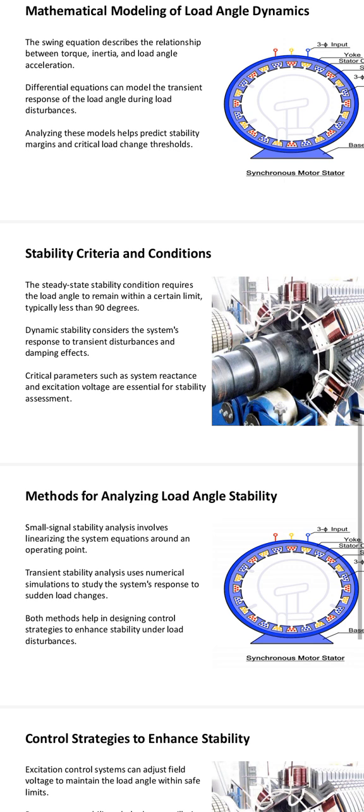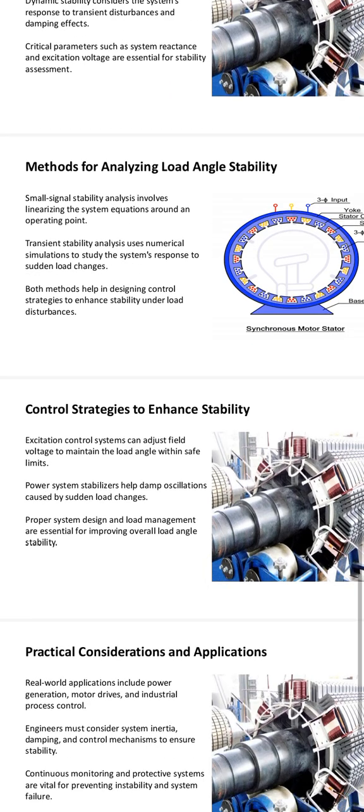Control strategies enhance stability. Excitation control systems can adjust field voltage to maintain the load angle within safe limits. Power system stabilizers help damp oscillations caused by sudden load changes. Proper system design and load management are essential for improving overall load angle stability.